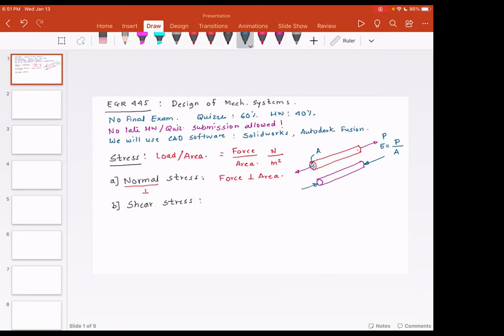If the stress is causing elongation, that stress is tensile. If the stress is causing compression, that stress is compressive. Now, at this point, I just have to clarify the difference between compressive stress and pressure. Pressure is used mainly in terms of fluids, like liquids and gas. So pressure is the compressive stress in fluids.